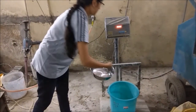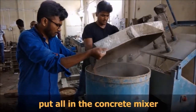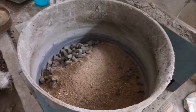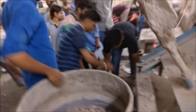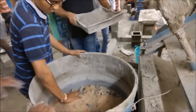After that, there will be a process of dry mixing. That is, we put all the contents in this mixer. Like here we are putting the sand, the coarse aggregate is already there, and then this will be the process of mixing. Then we will give a small dry mixing by putting the cement also, and then we will switch the mixer on.